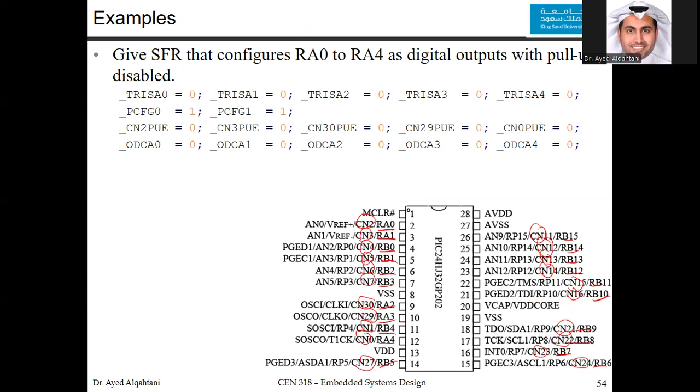So make sure that the correct one that you want to program, if you use a certain board with a certain bit, if you use, for example, this one, RB2, then if you want to activate or enable change notification, you choose number 6. And so on.